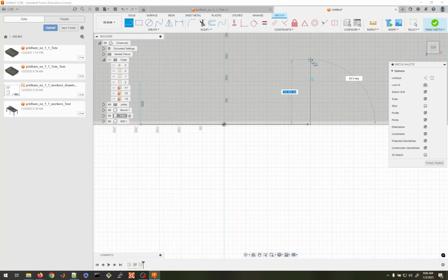And you can see it snapping to the grid rather than the corner. You can turn that off. I just hit escape again over here if you want, or you can just leave it on because it is helpful sometimes, and then just make sure you make the points coincident.